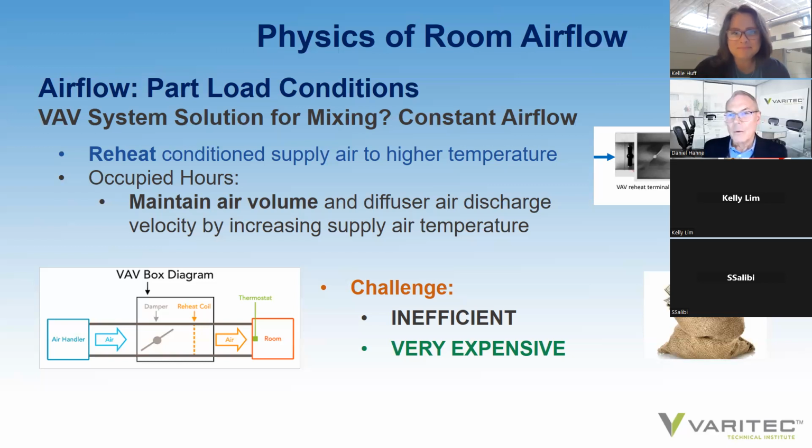Yes. In fact, all the Maricopa health clinics had a mixed air component at the coil. They were actually bringing return air back to the air handlers serving those designs. And the same was true with the Banner Boswell unit. It dealt with a mixed air condition. So in that application, there could be a challenge of reducing floor-to-floor heights unless they were 100% outside air solutions, because then you design at a lower CFM per square foot.